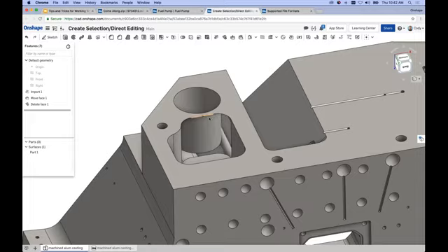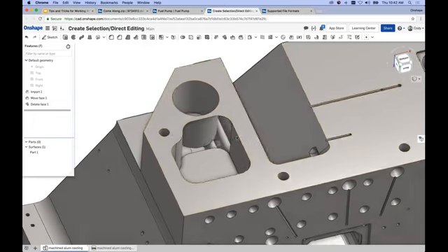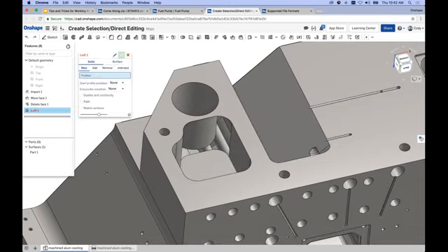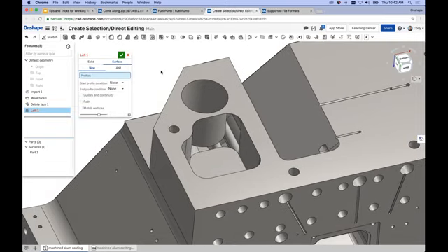Right, we have nothing but surface models or faces, and so now I need to recreate this geometry. Now, if I need to create a different type of geometry here, I may need to come in and construct maybe some bridging curves, or if the shape needs to be dramatically different, I may construct some sketch geometry that allows me to recreate those surfaces. But let's just say, for instance, that I've done that, and I'm ready now to bring this back into a solid model. I need to recreate the faces.